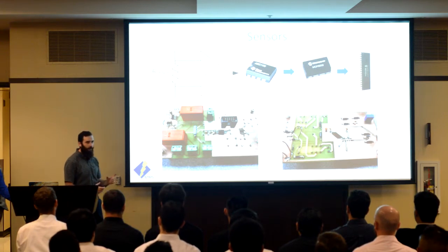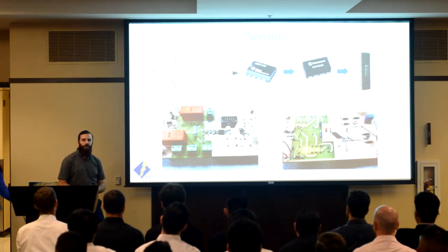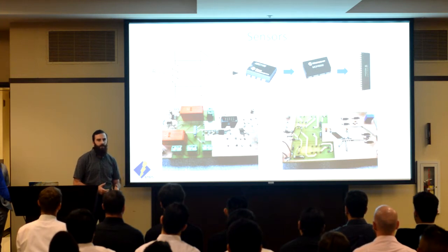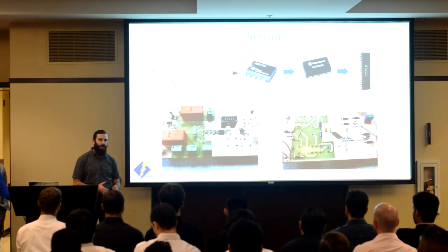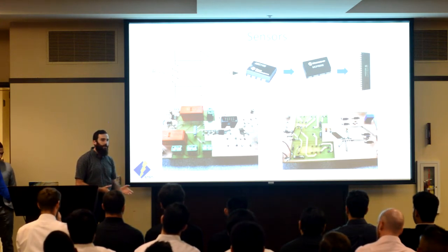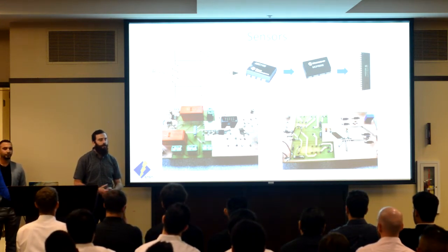We then take those small differential voltages and feed them into a 2-stage amplifier. The first stage of our amplifier is the AMC1100. We selected this unique chip from TI because it's an isolated amplifier, so the input stage is electrically isolated from the output. And this allows us to keep our 120 volt AC system separate from our low voltage electronics.